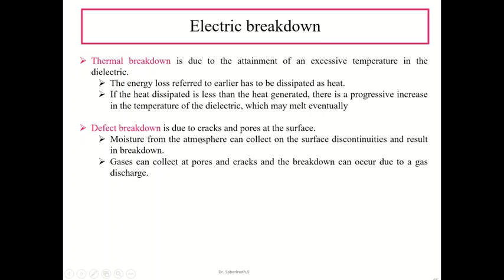So it is said that the thermal breakdown is due to the excessive temperature in the dielectric material, and the energy loss is the heat energy. If the heat energy dissipated is less than the heat generated, there will be an increase in the temperature of the dielectric, which in turn melts the material.